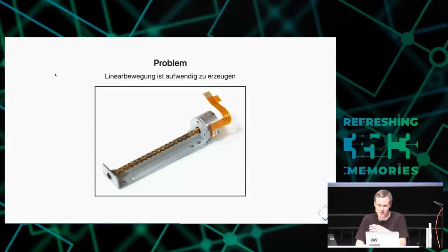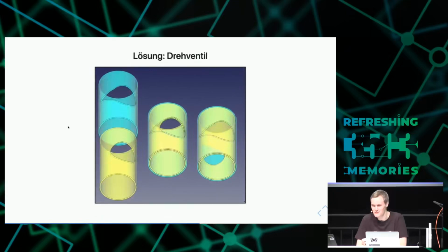I can also build it so that the motor is attached directly to the valve, but this is not good, because you need to put the spindle there, and then you have this nut which goes forward and backwards, which is pretty expensive in terms of parts and building.